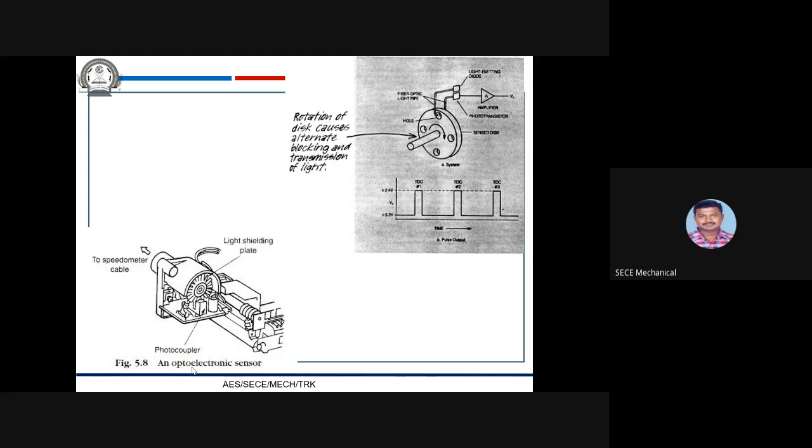There are many different kinds of optical sensors. The most common types are photoconductive devices, which convert a change of incident light into a change of resistance. Next are photovoltaics, commonly known as solar cells, which convert an amount of incident light into an output voltage. Next are photodiodes, which convert an amount of incident light into an output current. And next are phototransistors.